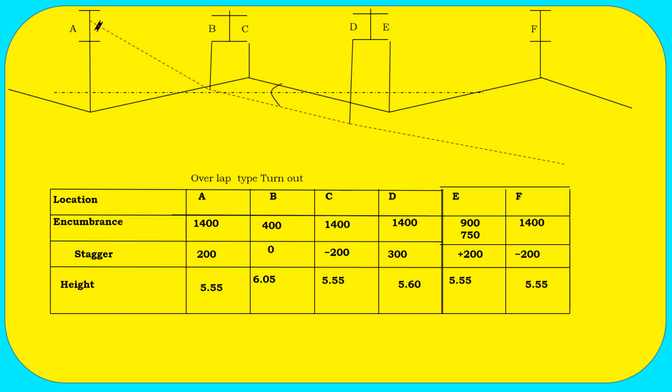From the pantograph horn. You know the pantograph horn has a curved side. The end of the pantograph is a curve. From there first it will catch the turnout OHE in the curvature portion, then slowly it will leave the mainline OHE and raise 50 centimeter above.